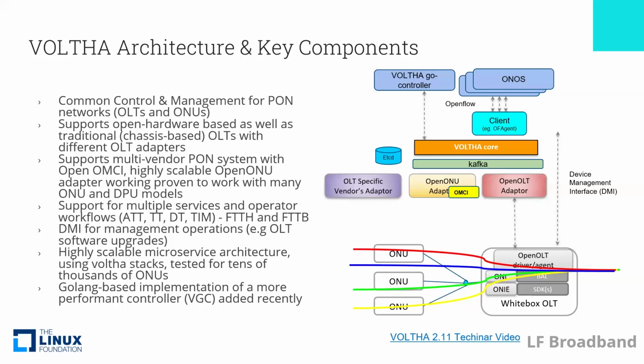If you look at some of the key components of the VOLTHA architecture, it has a common control and management for PON networks. It supports white box OLTs, as well as vendor-specific OLTs with the help of adapters. So you can have chassis-based OLTs with the help of different OLT adapters. But the current open source adapter is this open OLT adapter, which works with the white box OLTs.